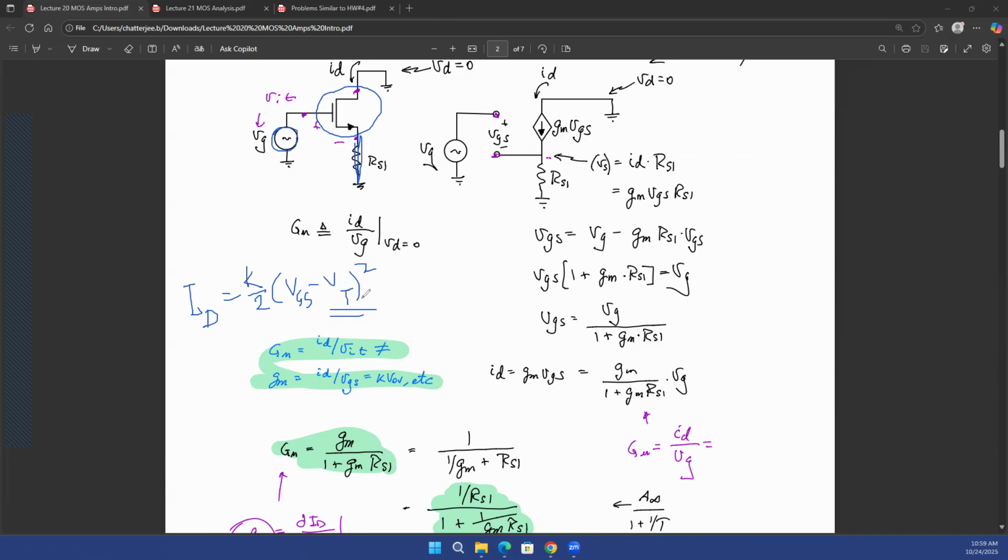If VT is larger, VGS minus VT is smaller, which means that my ID current will be small. ID is basically the current flowing through the MOSFET. If I did not have the resistance over here, whatever VT my transistor had will determine the ID current that I'll be having. But if I have this source resistance, the advantage that I'll get is that, let's say my VT is higher than what I expect, which means that my ID will be lower than what I expect, right?